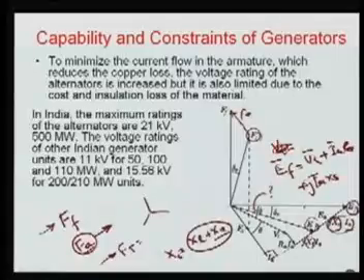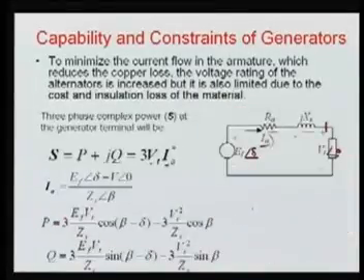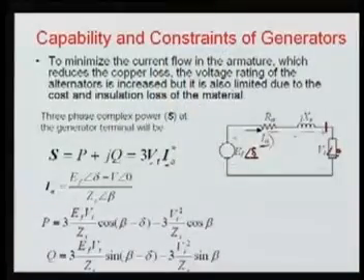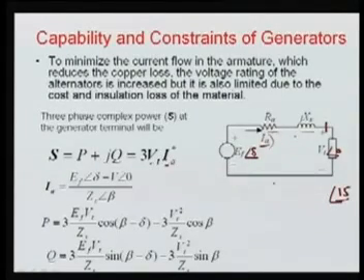The power factor angle is nothing but the angle between voltage and current. However, this load angle is between two quantities of the same unit, means voltage and voltage. So this is delta, with reference to this voltage at 0. If you are taking, let's suppose, 15 degrees for this voltage, then this will be your delta plus 15.